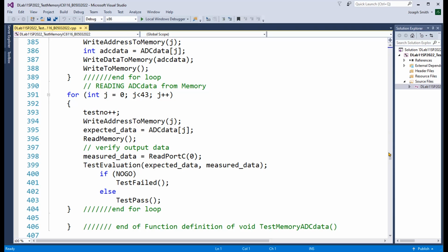You can hit two problems. One is the control box. Second, the memory IC. When you do the lab in the class, you can use one control box. Try switching out different control boxes. Exactly. And if that doesn't work, maybe switch out the memory. Exactly.